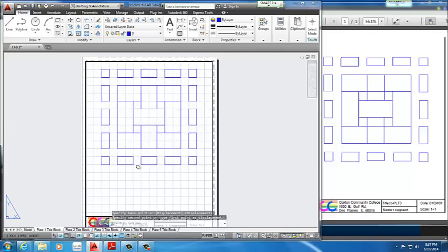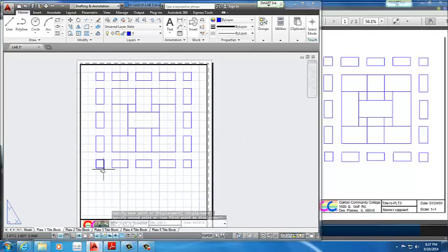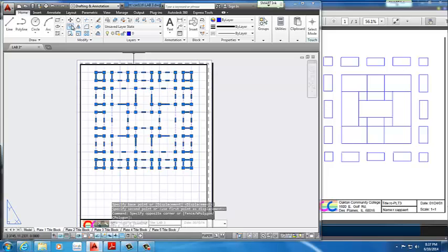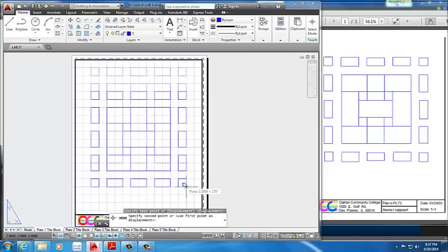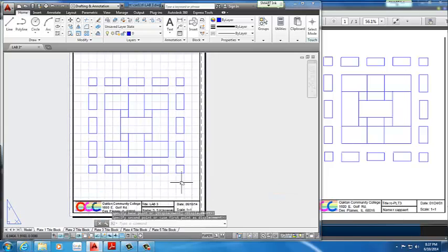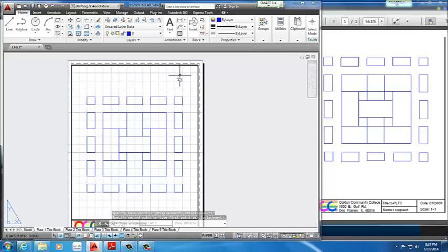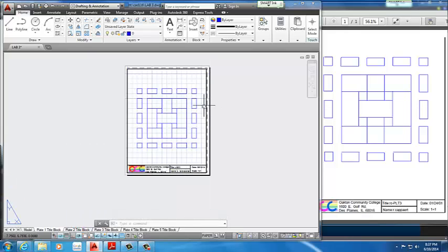So I'm going to move this line to the right. I also want to select the line again, go to the move command, and I want to stretch it downwards by selecting a blue point and just moving it back. And that gives me about 3 boxes at the bottom and a little bit more than 3 on top. And that's exactly where I want it. So I'll stretch this line. It's actually centered.